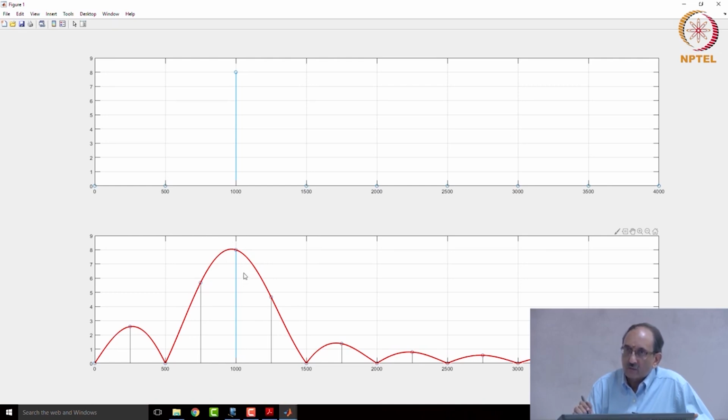It is slightly shifted, and again this shift makes sense because this is analogous to what we had seen in the context of the resonator. If there were one pole by itself, there would be no shift in the peak, but because of the tail of the peak due to the other pole, this pole's peak got shifted and vice versa.